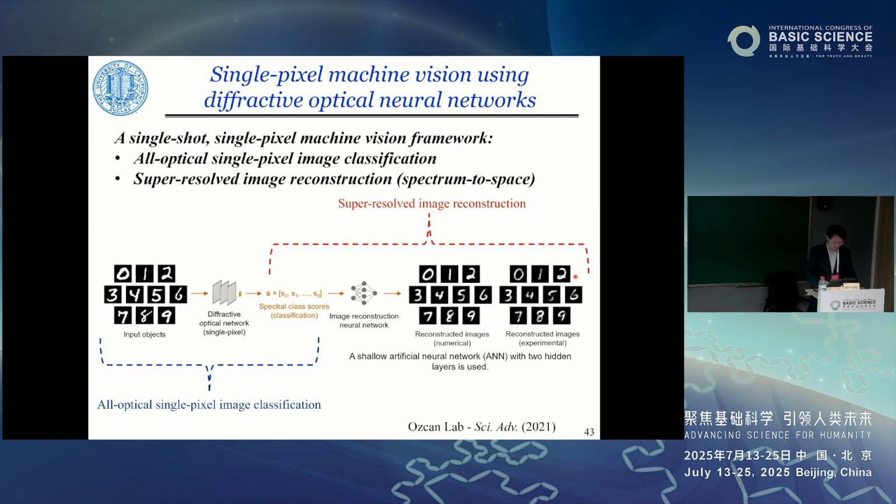From a system-level perspective, this allows n different users to hold n different decryption keys, with each key capable of unlocking only a single class of the optical data while keeping all other classes inaccessible. This is achieved by incorporating label supervision during the training process. Both encryption and class-conditioned coding are directly integrated into the passive diffractive structures, expanding the potential application of the architectures in secure communications and privacy-preserving hardware.